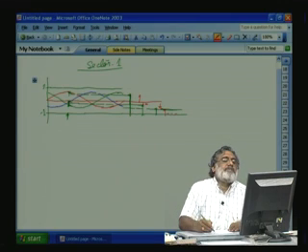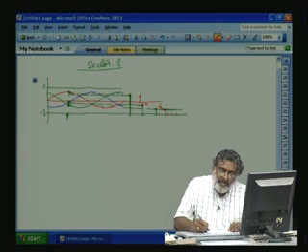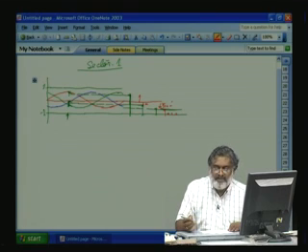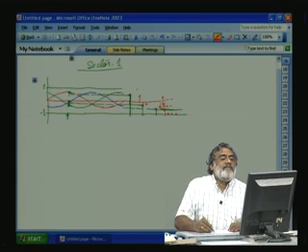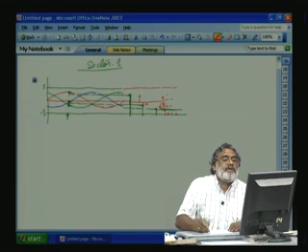But if you compare with the sine triangle, till this period, as the triangle waveform increases, we are sampling from here. As it moves from here, sine is greater than the triangle. So, till this period it will be plus plus plus. After that, this will go negative. C phase will be from here to here, plus plus minus. Then from here to here, it will be plus minus minus. Then, if we extend this one, from here to here it is minus minus minus.